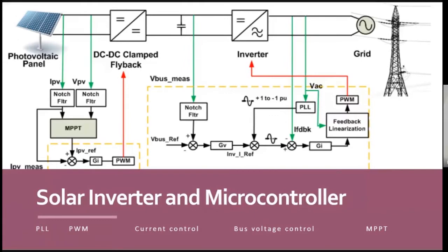In this case, we will need a microcontroller that is more complex and more featured than in the previous application. That means it is more complex than a normal MPPT application. Here, it should work along with the grid, as I said. That means it should keep up very fast with the grid. So in this case, we need a faster microcontroller. A normal 8-bit microcontroller will not be enough for these applications. In such applications, most of the products are using 32-bit microcontrollers. We'll discuss high computing capacity microcontrollers and their features in later sessions.